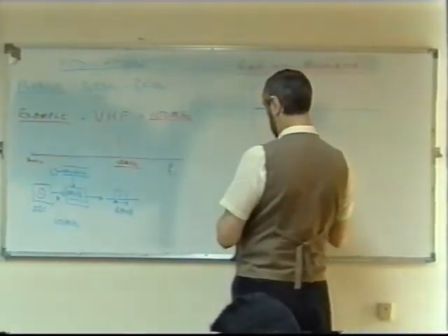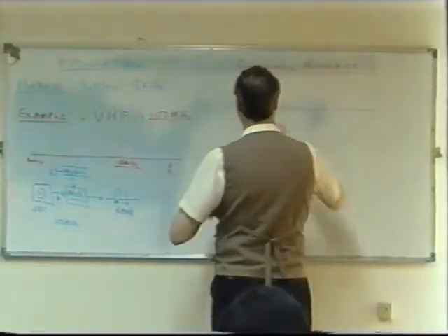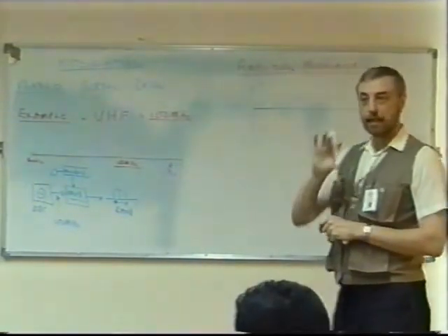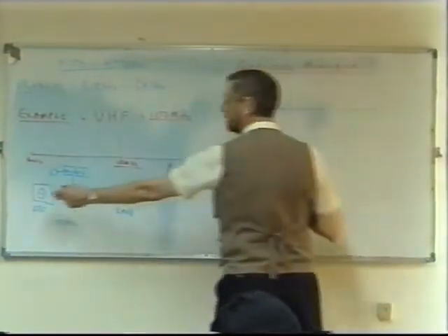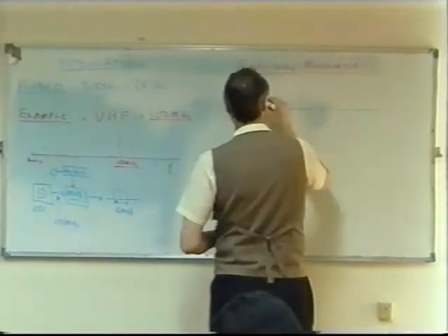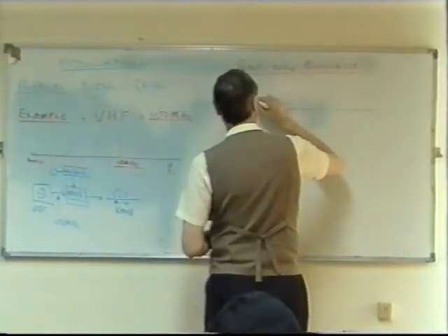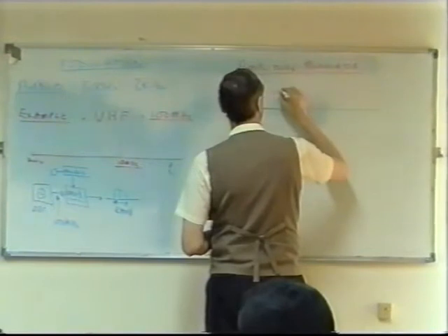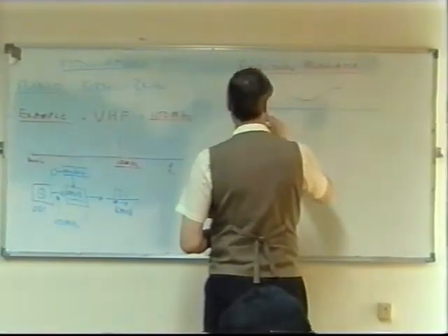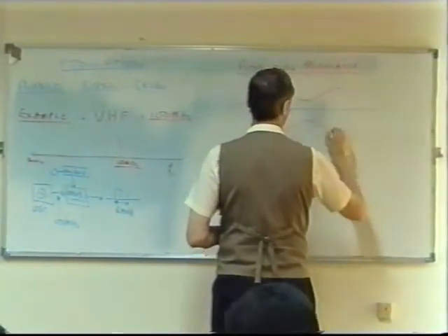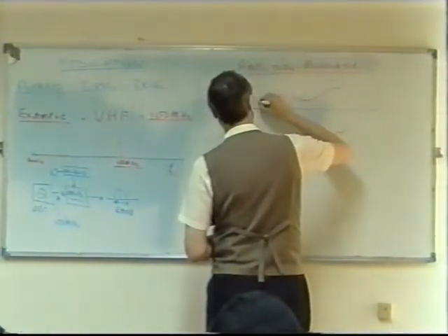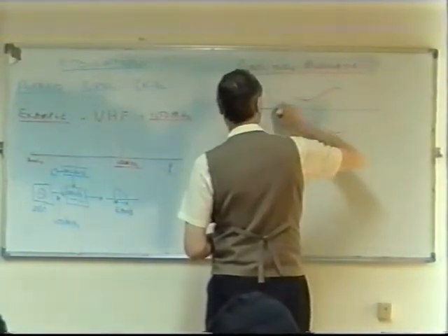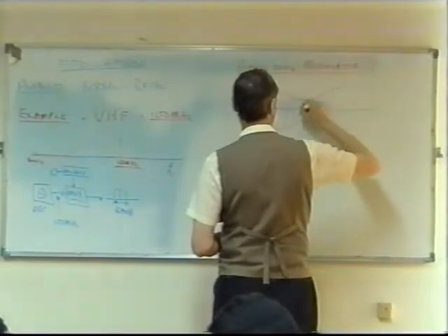You don't have to necessarily remember these. What we do is we take the carrier, that is this frequency here from the oscillator, and we change its amplitude, something like this. And we change its amplitude according to the signal that I'm using for modulation.